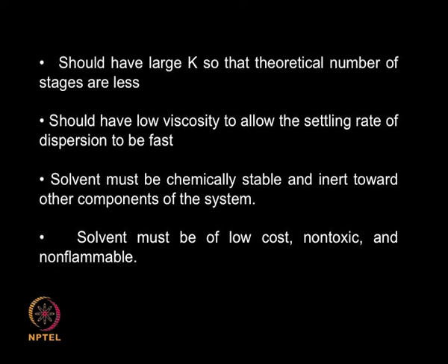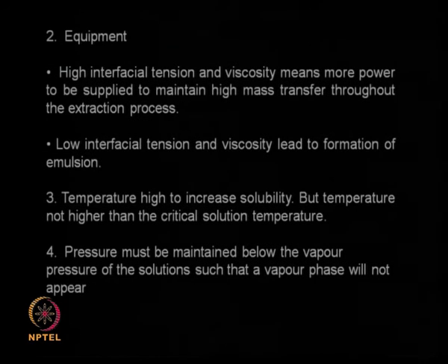So, it should be totally inert with respect to other components. It should be cheap, should not be toxic, because we are talking in terms of using a large amount of solvent, and it should not be flammable as well. So, that means it should be non flammable. So far we looked at the solvent. You see, solvent selection is a big challenge and it should satisfy a large number of conditions.